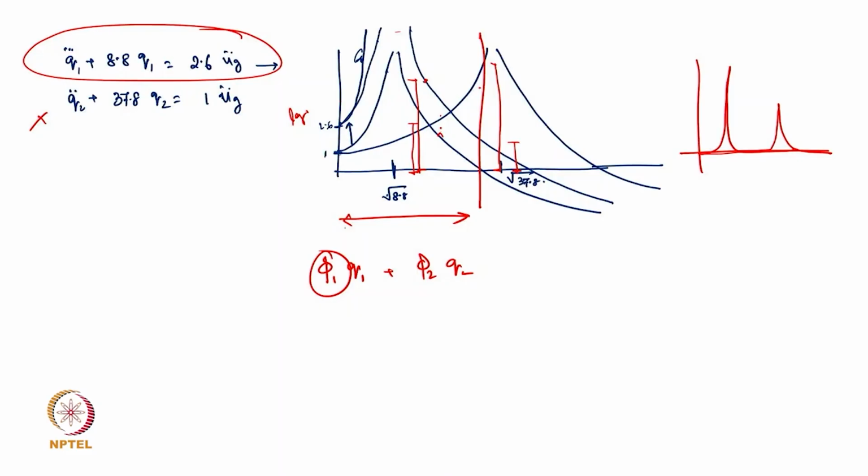But in most cases, if you come to the earthquake case, are we okay with not considering the higher modes? Now, earthquake is not a harmonic excitation; rather it's a band of excitation. It's not just a sine omega t. It is a combination of several sines.